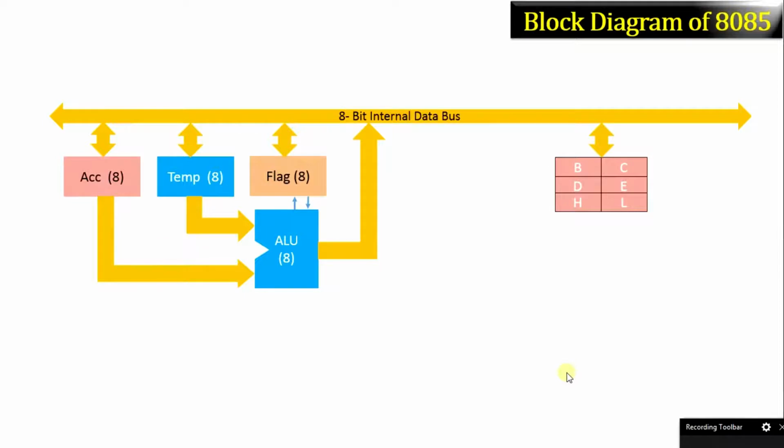Whenever we want to make it programmable, we have to write the program and store it in memory, because inside this IC or this circuit we cannot store large data. Whenever we write a program, obviously the program length will be larger than 8 bytes or 10 bytes. So we cannot add that much storage inside this IC. We have to make a provision to store the program outside of this IC, and that outside of the IC is nothing but memory.